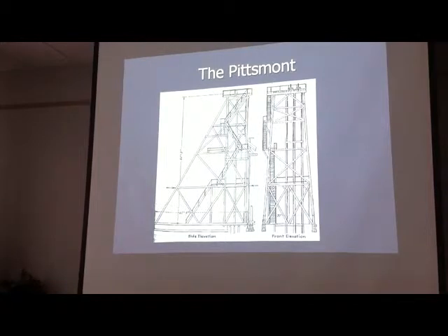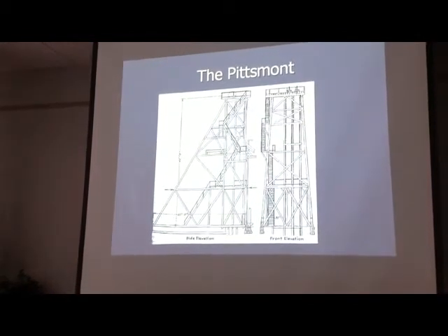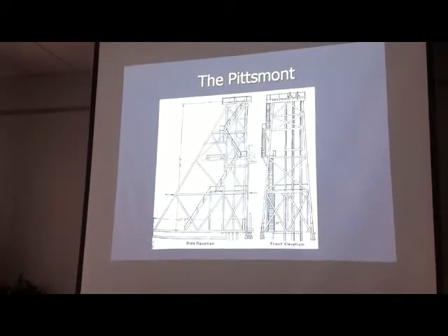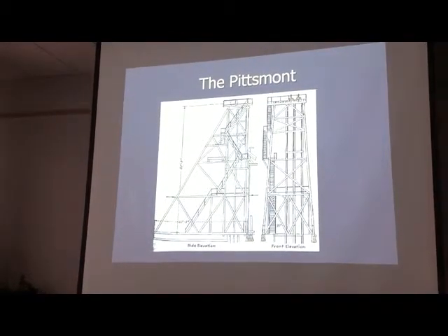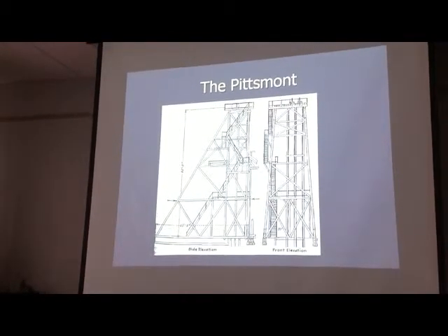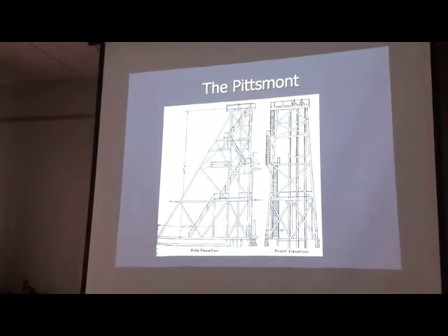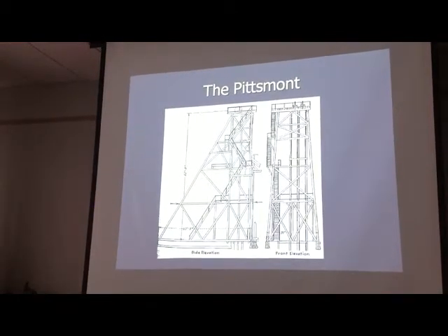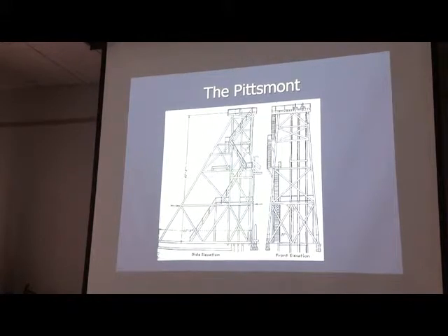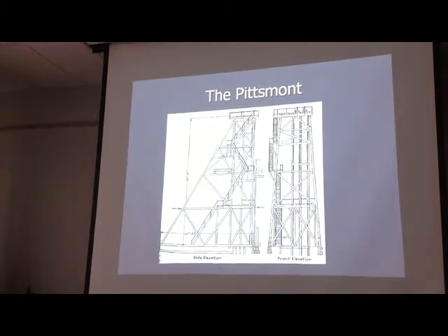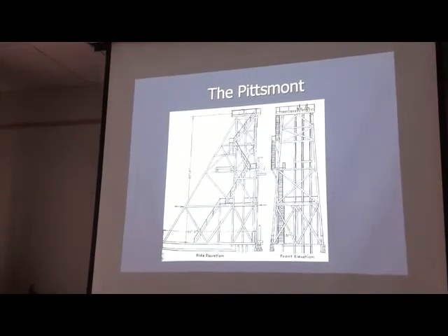They started with a fairly small head frame. This arrow here to the top was the original head frame. And they were using cage hoisting. Later on, they increased it to 82 feet, as you see here, by another addition. And then when they went to skip hoisting, it went up to 94 feet. So they remodeled this head frame 3 times just by jacking it up and adding more timber underneath it to get the necessary height so they could move the ore.